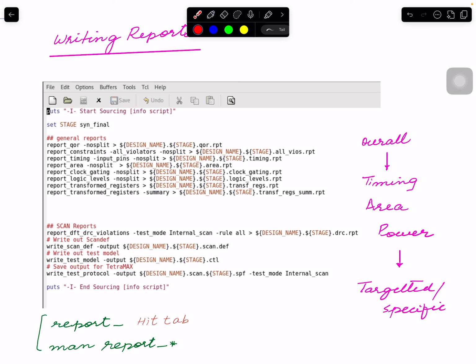Okay, how the overall timing looks like. Okay, basically it always comes down to these. I mean, remember these were the three constraints: your timing. Okay, you define clocks, whether you are hitting that frequency or not. Then your area. Okay, area, or sometimes I also call it a floor plan or a layout constraint, or area constraints. Okay, area you are mainly interested in how many cells I have, how many standard cells I have, how many macros I have, what's the variance, and what's the area of them.